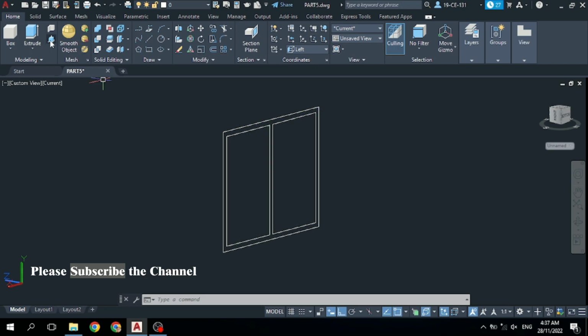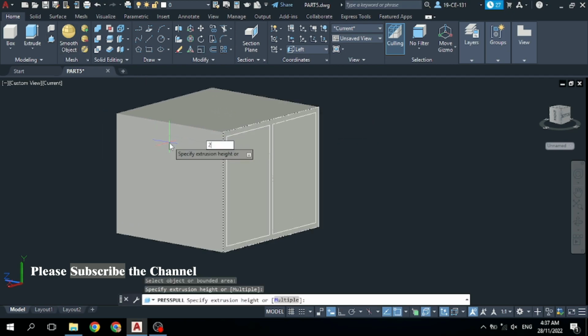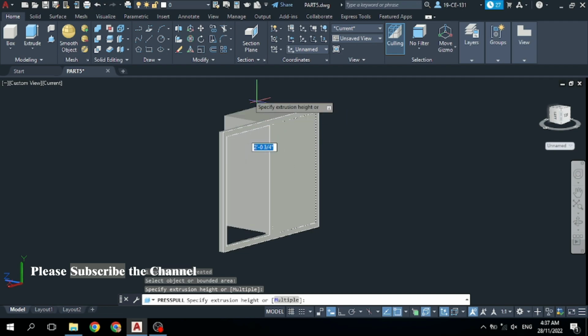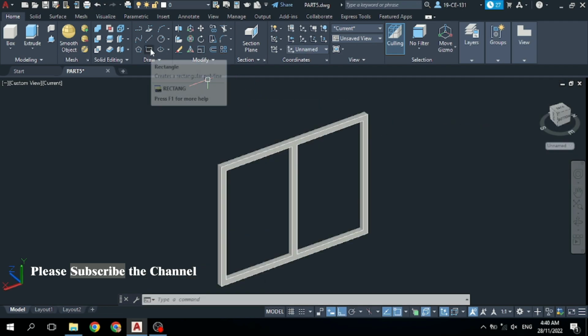After that click on press pull command. You can see this press pull command and select this line and go to this side 2 inches, type 2 inches, then press enter. Now you can see it is 2 inches, and then click on this press pull command and go to this side to open this area. Now you can see it is opened, and also this line, and go to open it. And after that click on this rectangle command.